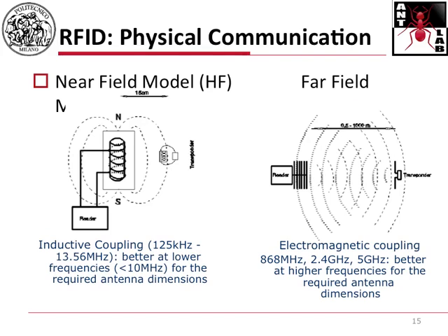The idea is the following. You have a reader which transmits some kind of wireless signal. This signal is an electromagnetic wave, which propagates in the environment, and the tag here, or better, the receiving circuit of the tag, is shaped as a coil.